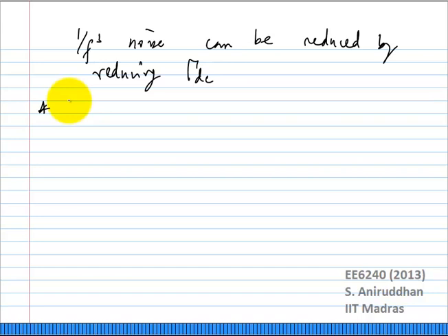Because even if you look at the LTI model, the simplest model, you put in broadband thermal noise, and the tank shapes it as 1 over f squared. So how do you think you get your flat noise region? What do you think?